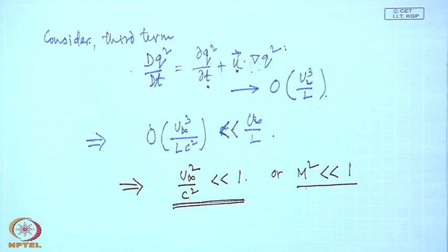Anyway, this is one of the conditions, the Mach number, and we will see that quite often people answer that, okay, what is incompressible flow? Incompressible flows are those flows for which the Mach number is less than 0.3. That is a common answer, though of course the answer is completely wrong, but the source is here. The Mach number is perhaps the most important parameter which decides whether we should treat the flow as incompressible or not.